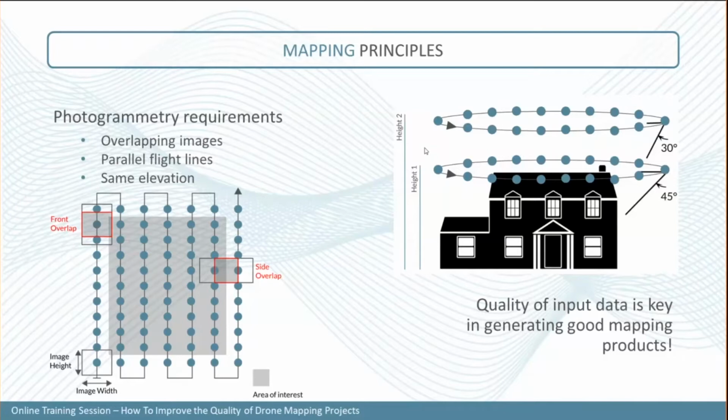If that's not the case, what you can always do is try to fly your project in different blocks. For all the sections that are at a similar elevation, you can do one block there. Then if you have a slope, you can just raise the drone elevation and map the other section,